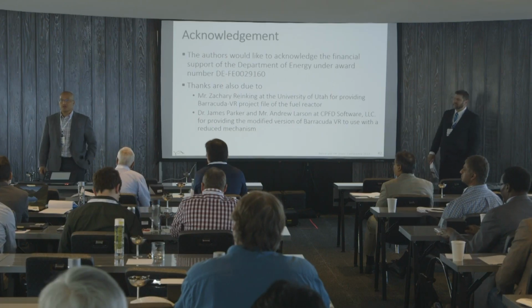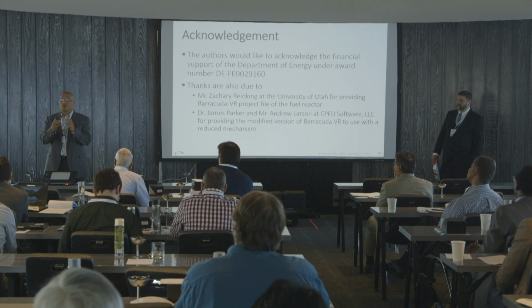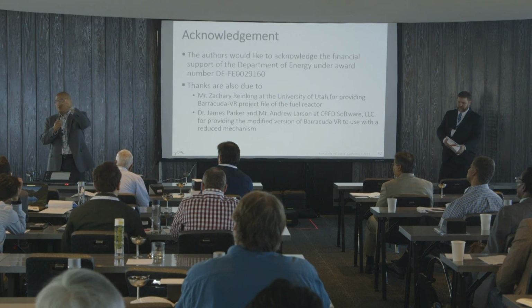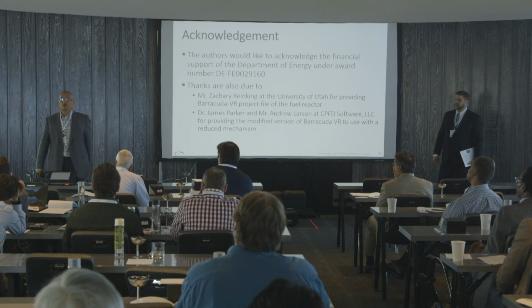Nice presentation. My question is regarding the ash and the coal. In terms of the CPFD boundary conditions, how are you rejecting the ash from the coal once it's reacted? You start with the coal and define it with those species: CHNS, volatile species, ash, and then moisture.